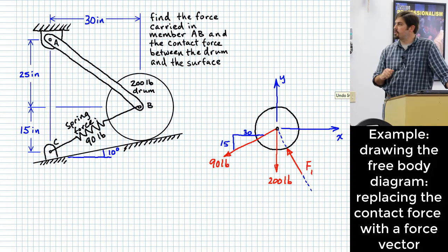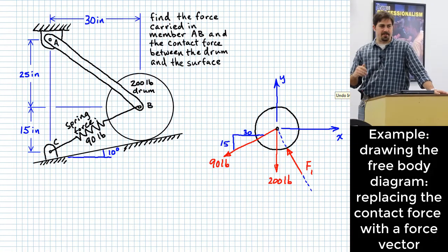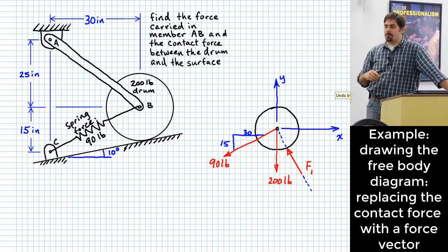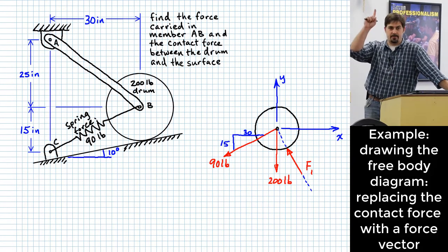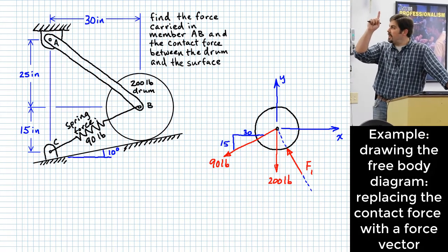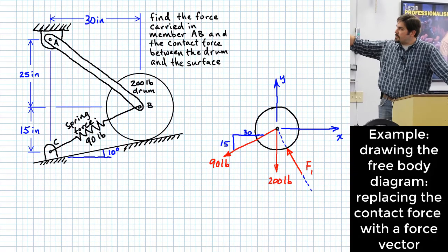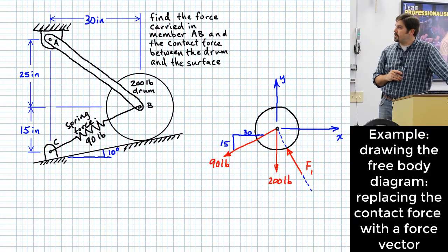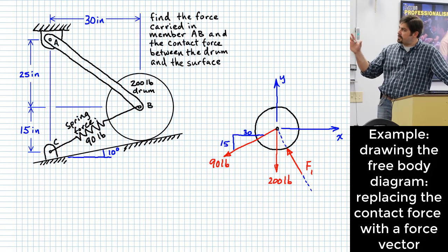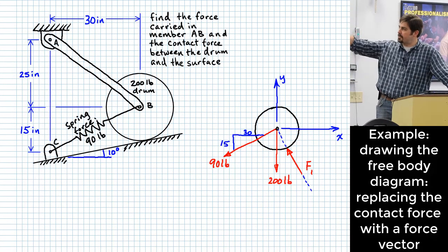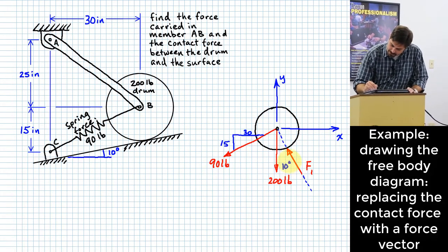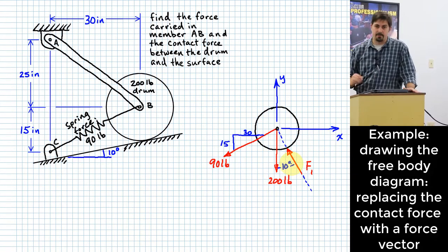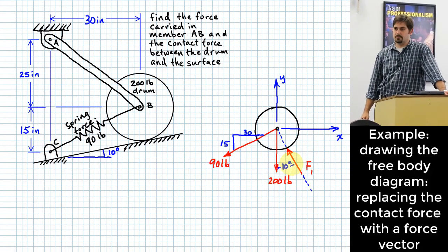What I like to do in these situations is take it to its limiting cases. What if it wasn't 10 degrees? What if it was 0 degrees? Then F1 would be acting straight up, right? So whatever we pick as far as where we measure this angle, it should end up having a consistent direction if it goes to 0. And what I would say makes that happen is if I put the 10 degrees right here. Would you agree with that?